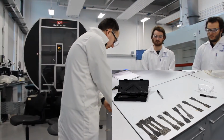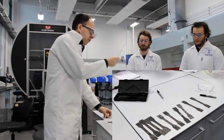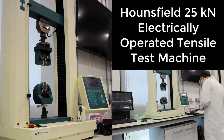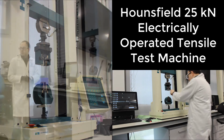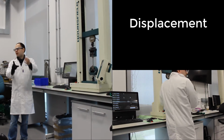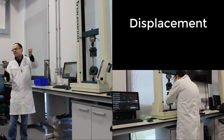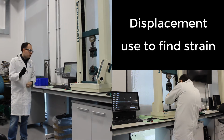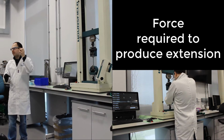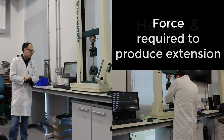You have to work out engineering stress and true stress strain curves. We've got 6 different types of tensile bars. First of all, we've got the plain one. I'm going to start by putting this on the machine. Of course, it measures the amount of displacement, the amount of extension, which you can convert into strain. And it also measures the amount of force that's required in order to create that level of extension.